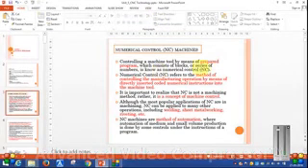First of all, the numerical control machines. Controlling a machine tool by means of a prepared program, which consists of blocks or a series of numbers, is known as numerical control. That is, numerical control refers to the method of controlling manufacturing operations by means of directly inserted coded numerical instructions into the machine tools, that is, with the help of the punched paper tape. The numerical control machine consists of two main components, that is the punched paper tape and stepper motor.